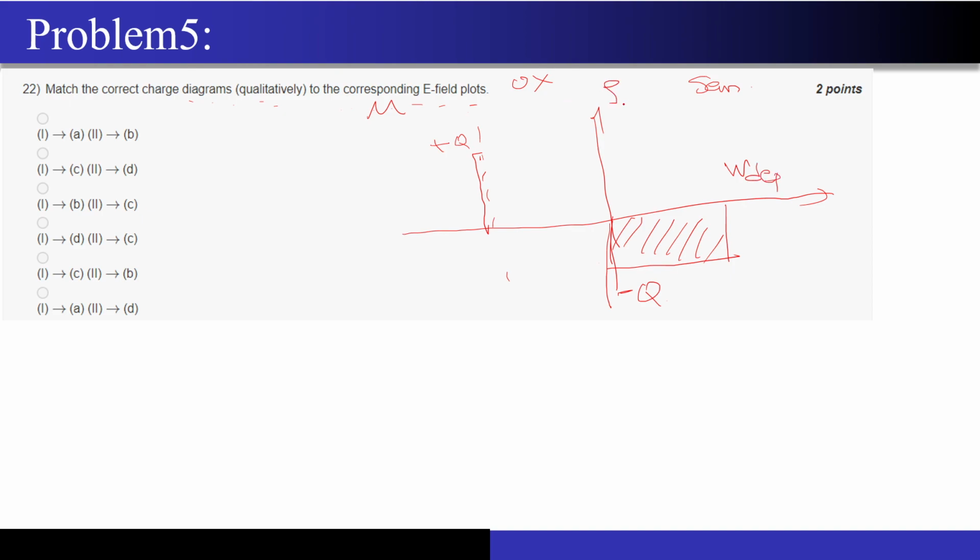And this is your rho on the y-axis, and this is your x on the x-axis, right? Now, how do you find the electric field profile from the charge profile that is given to you? You integrate it, right? You integrate it and just forget about the constant as of now, because they are not asking us the value. They want the shape of the profile, right?